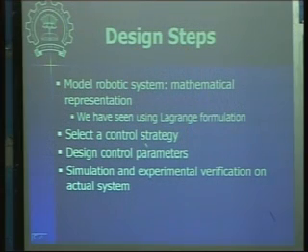Okay, the second thing is selecting the control strategy. Now, here is where you have to put in a lot of effort. First, you have to have a good understanding of the dynamics. So carry out some simulations, understand the dynamics of your robot. Okay, a step response or some kind of response, you see how for a given input the robot responds, and then based on that you can say what kind of controller you will have to select. Okay, and then you carry out this selection of a controller step.